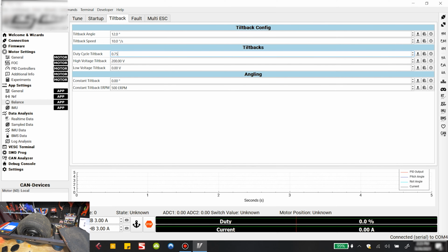I think that's fine. It's currently faster than I want to go on this. I've gone 16, 17 miles per hour, and I think I hit maybe 65-ish% duty cycle at my current weight of 182, 181, something like that. I'm in the low 180s. And so that's something to take into account. I recommend leaving it at the default. If you know that you can go higher after you've used this machine and experimented with it, fine, set it higher. But for now, I'm leaving it at that.